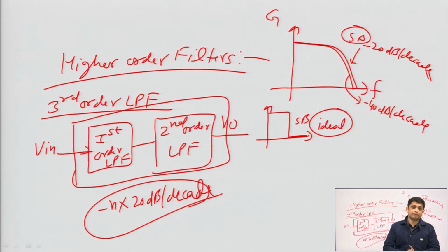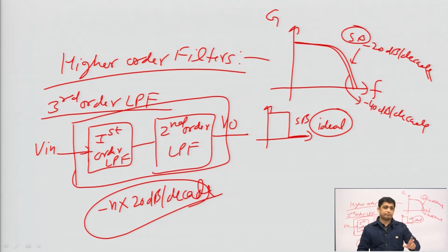So, accuracy is the problem, because when we theoretically calculate some value of resistor and when we practically design that circuit on a breadboard in the lab, there is a difference, because we cannot take the actual value of the resistor, as there is some tolerance of 5%, 10%, 20%. So, there is some variation in the component values. That variation may be due to the temperature also, fine. So, due to these things, there is some difference between the values calculated theoretically and the circuit designed practically on the breadboard.